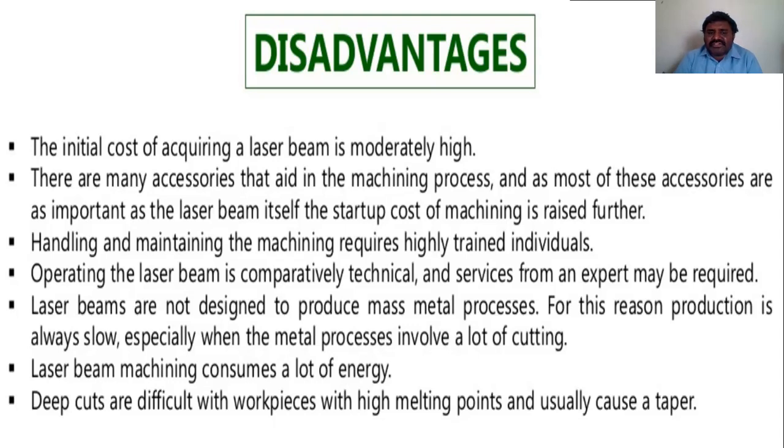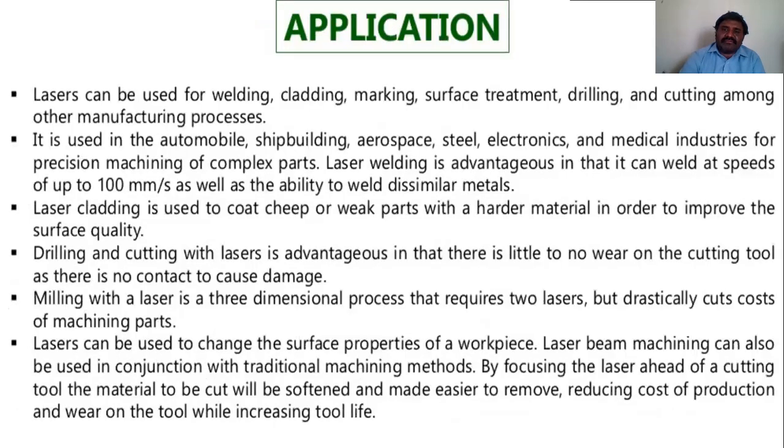And laser beam machining consumes a lot of energy. That is the reason we are using lasers of gas, solid state, and excimer types. A lot of energy will be generated here. That is the reason it can also be harmful to the body. So due to that, machining can only be carried out carefully here. And deep cuts are difficult with a workpiece with a high melting point. If the melting point is high, depth is very, very difficult. Okay, and it usually causes a taper.